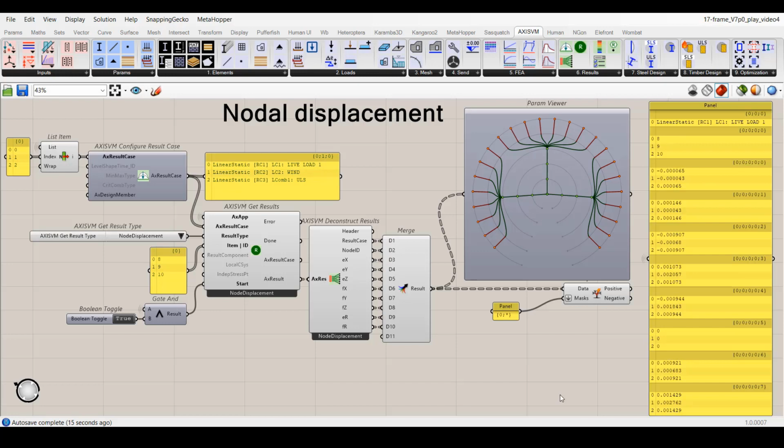For example, the displacement in x direction is stored in a list for node number 8, 9, 10 in this order. To make it more clear, you see the encircled region that contains the information about the result cases. The next level contains the node IDs, and the following 8 sub-branches contain the result components. A very similar data structure is used for the nodal support reaction forces.